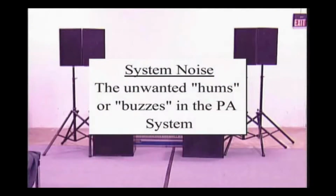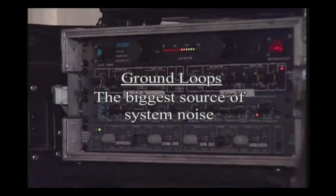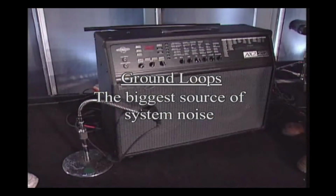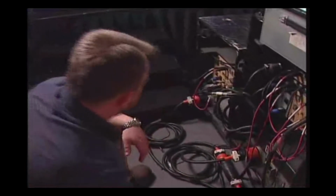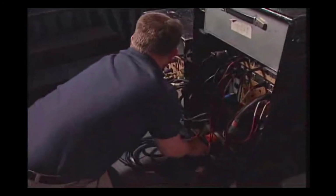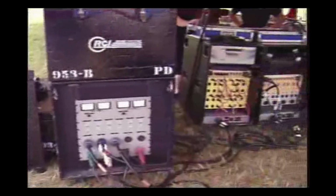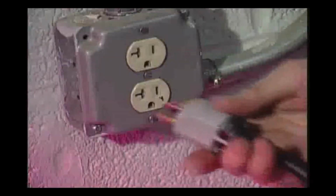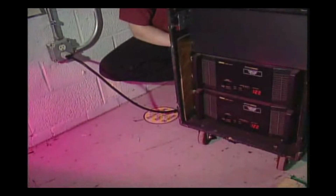System noise is the term we use to describe the unwanted hums or buzzes in our PA system. The biggest source of system noise comes from ground loops, and ground loops typically come from improper system grounding. Interestingly though, the very thing that's used to keep a system safe is also the culprit behind a lot of the system noise, grounding. So when we say proper system grounding can go a long way towards solving typical system noise, we're not just talking about making sure all the plugs are pushed into the wall sockets. Let's talk first about what grounding is.